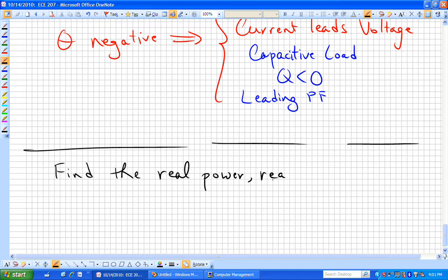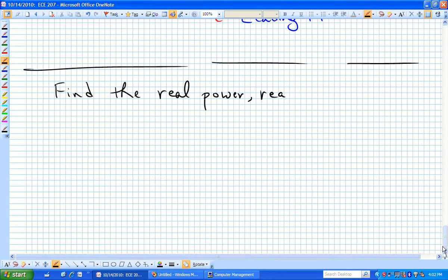They may say, I don't care, you're off in your own little world, you have a lot of apparent power that our power lines are having to be designed to withstand, and so we're going to surcharge you for that also. It's just that most industrial users have positive reactive power, a lagging power factor. But if you had a big capacitive load, they would probably give you a surcharge also.